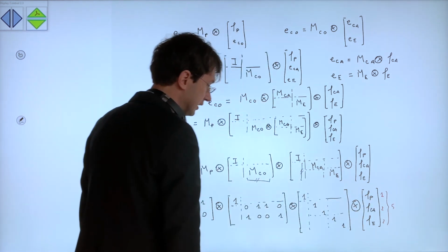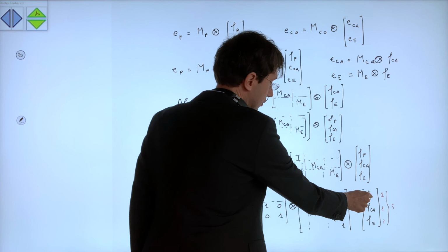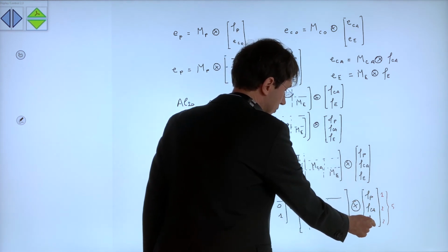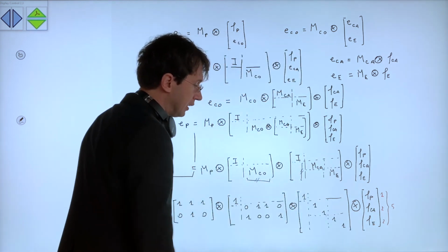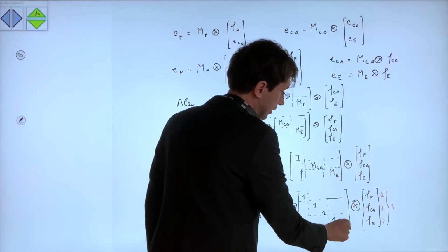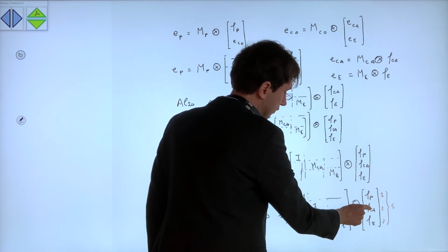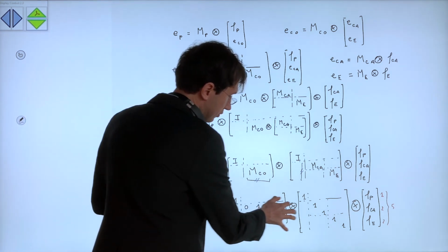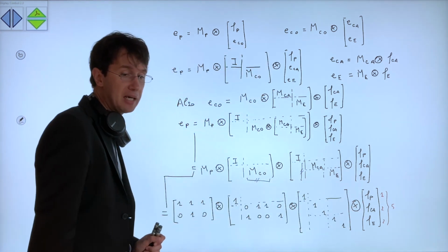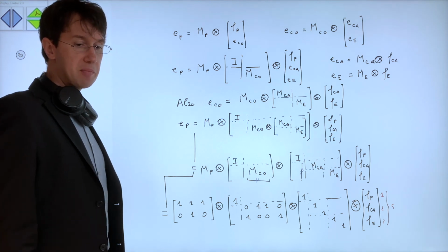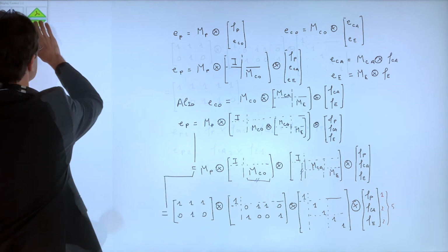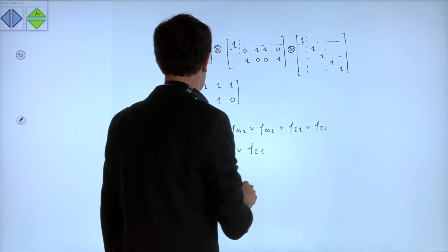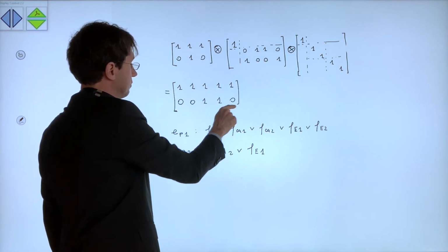This expression is in terms of faults from the picker, faults from the camera, faults from the encoder. And the size of this vector is 5, because we have 1 fault in the picker, 2 possible faults in the camera, 2 possible faults in the encoder. So you just need to do this computation in order to get the final matrix of the entire system, explaining the effects and faults relation. And this final computation goes smoothly, like this, and in the end you get this expression.